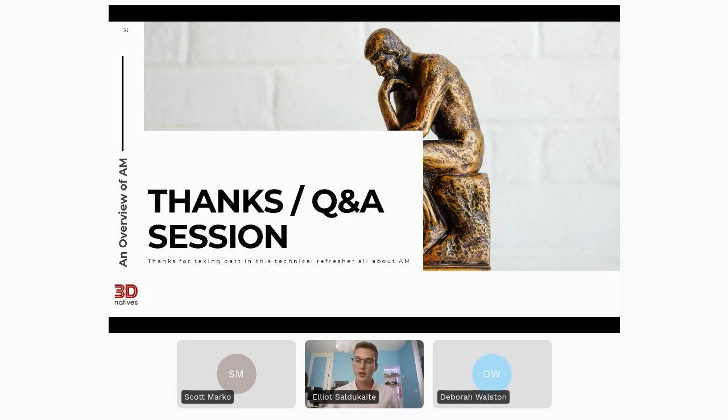Okay, so another question is, can you please give comments on continuous fiber reinforced 3D printing, technology, status, market demands, etc.? Indeed, continuous fiber reinforced 3D printing is a big topic, especially in FDM or FFF 3D printing, so extrusion-based 3D printing. The idea is to actually inlay a continuous fiber, whether that be a glass fiber or carbon fiber, in your 3D print. So you're printing with polymer and infusing a continuous fiber to make sure your 3D print is way more resistant to mechanical forces along the X and Y axes.